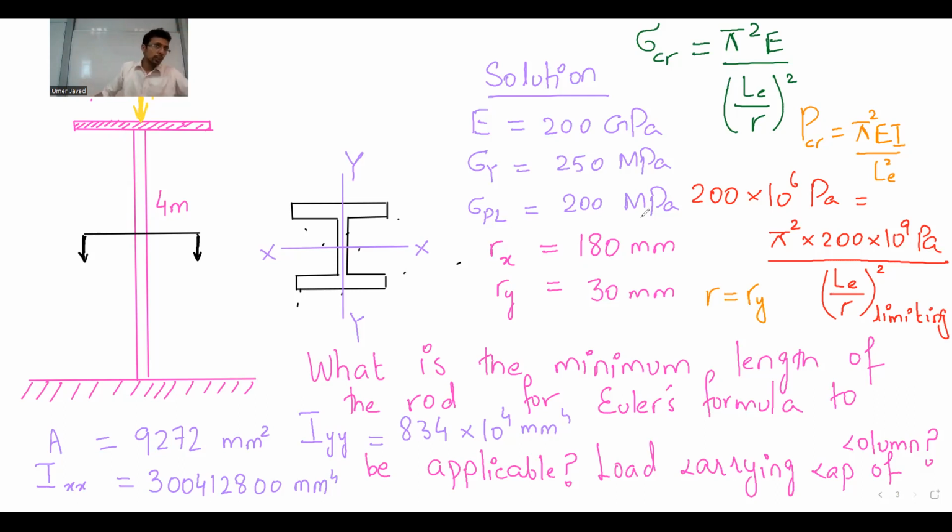You will definitely say it will buckle where the moment of inertia is less, where it is easier to buckle, in simple English. So remember that when you have lower moment of inertia, the object will buckle there, not where the moment of inertia is higher. The ruler is weaker. For example, it will buckle like this, not like this.